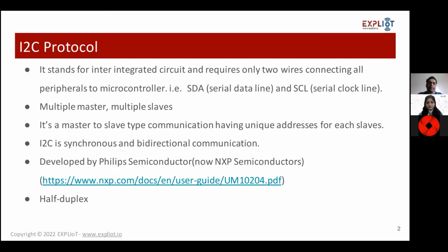The SPI protocol, if you have watched this video or attended the webinar on SPI, is a faster communication where you have 4 dedicated lines, namely the serial clock, the master input and master output data, what we call MISO and MOSI, and the chip select or slave select, where I can connect multiple slaves from different pins of the microcontroller. But coming over here, the 2 challenges that UART and SPI face are in terms of extended hardware and the synchronization problem.